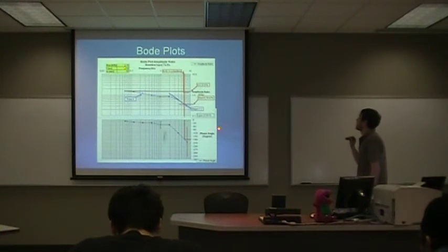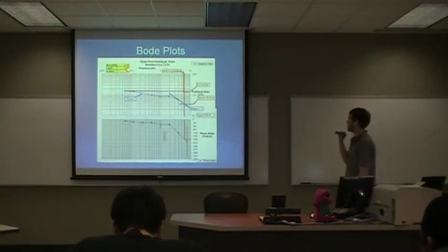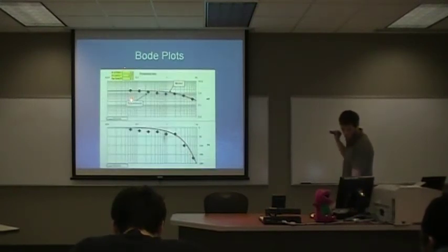Right here is a Bode plot for a baseline input of 72.5, and from this, of course, we did the same technique of starting from 180 and going up, and we were able to find our FU and then also find the three parameters that we'll use later, which are the ultimate controller gain, tau, and T naught: 2.78, 0.58, and 92.